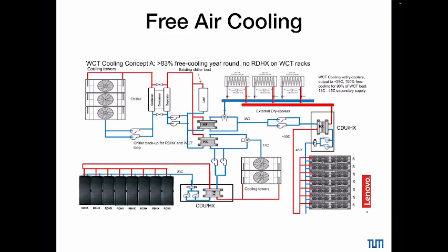There are two concepts here. The first one is the back door, rear door cooling. So you have one door, which is basically cooling down the air used in the server with the help of a water circuit, right? So basically we see that here. We get cold water of 23 degrees going into the doors, and then out of the doors we get hotter water. It goes through a heat exchanger to cooling towers.